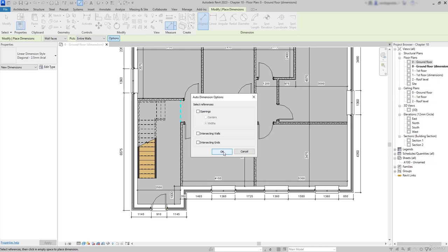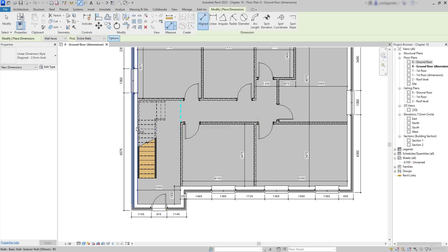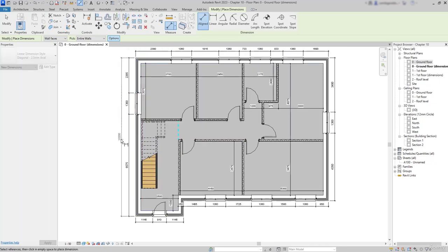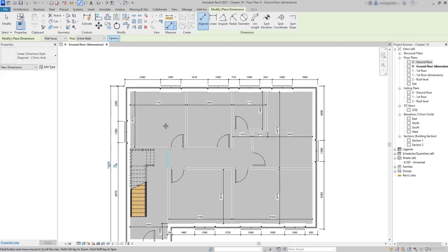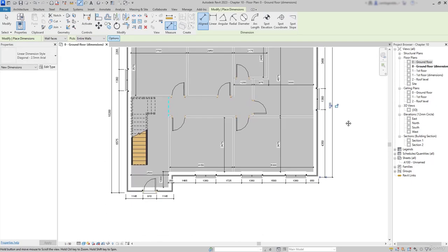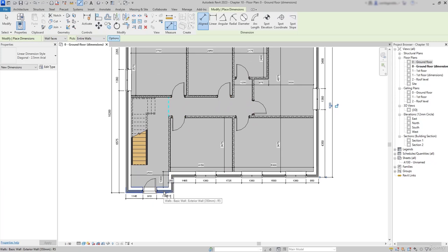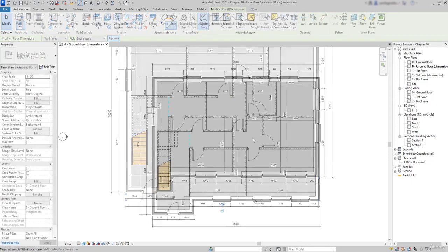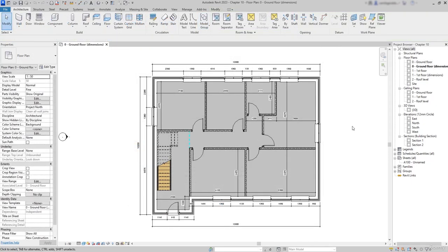Click on OK. So I am placing another dimension after the ones already exist there, and you can also see that the pointer snaps in order to respect a specific spacing between the lines. Here in the main facade, first I insert a dimension for this wall, and then what I can do is click and drag on this grip to this face. So, the ground floor is finished.